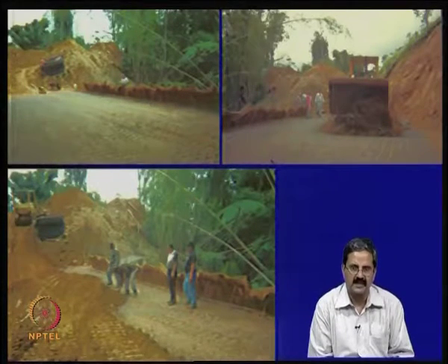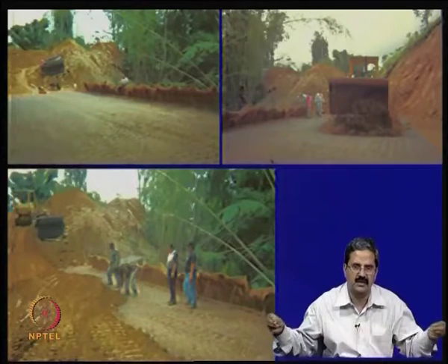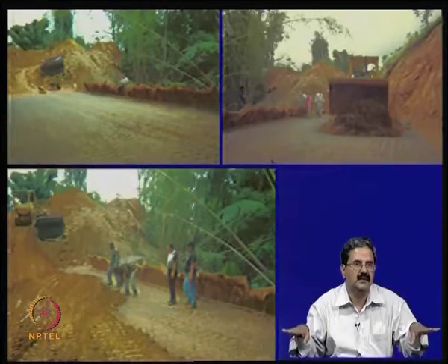But if there are seepage pressures or some horizontal force, such as earthquake force, then the length of the reinforcement will be high. The length of the reinforcement required, as I said, could be say 0.7 times the height, depending on the slope angle and the phi friction angle of the soil. You can get the required angle.